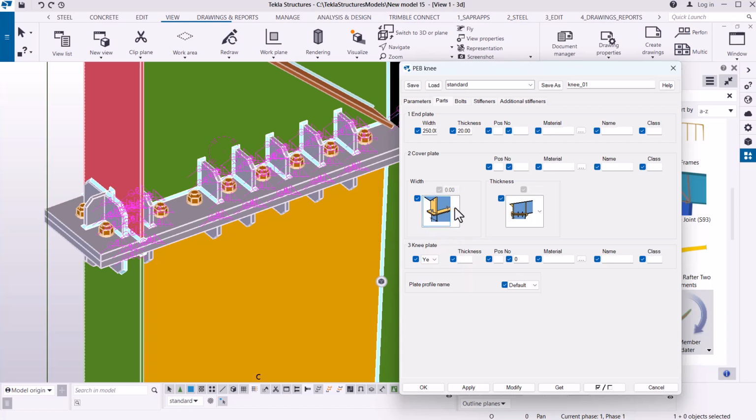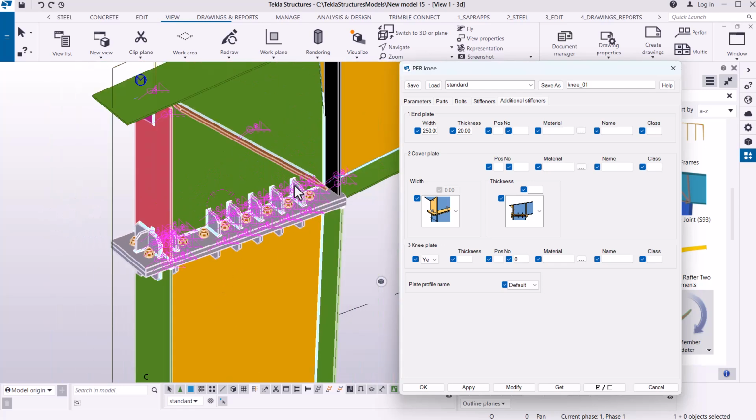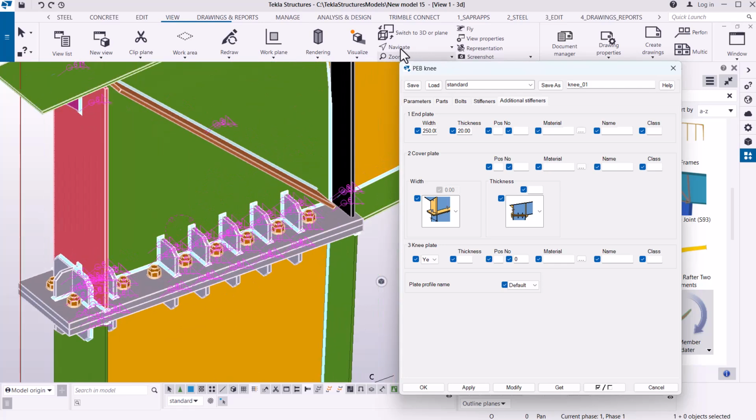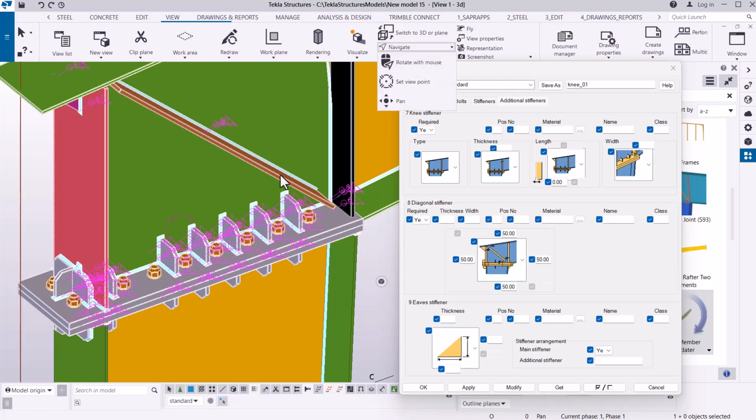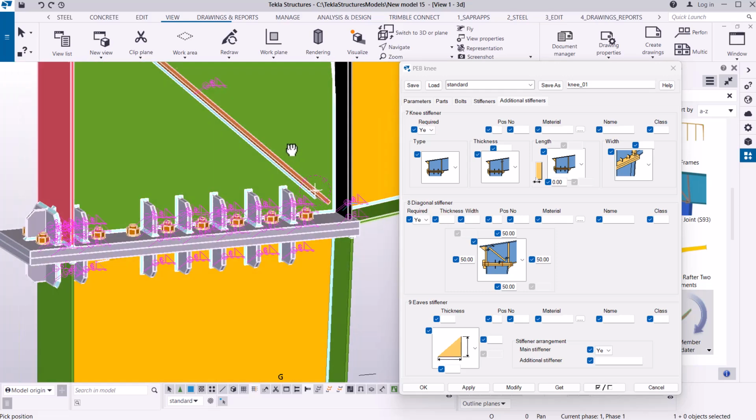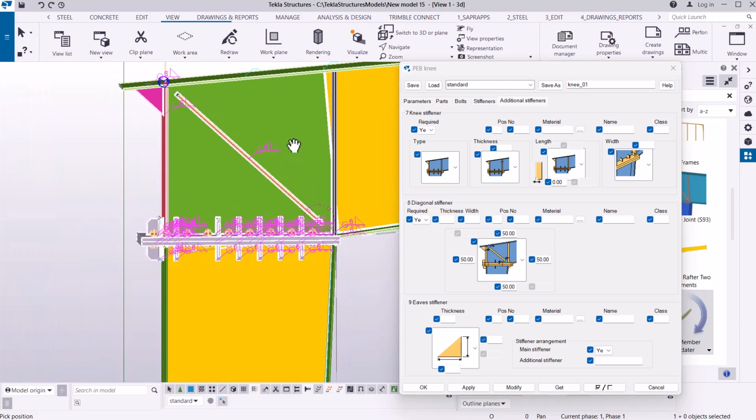If we pick on that, the width and thickness can be keyed in there, and all that. So this is where you manipulate everything and change the material on that spot. And additional stiffener, maybe you want this stiffener to not clash with these stiffeners here. So what I'm going to do, I'll show you how you can adjust it. Let me just double click there.